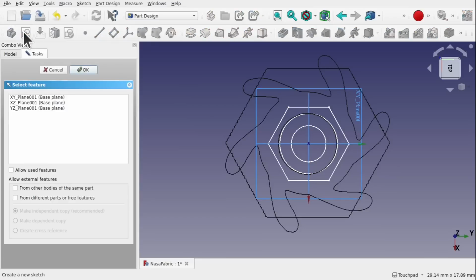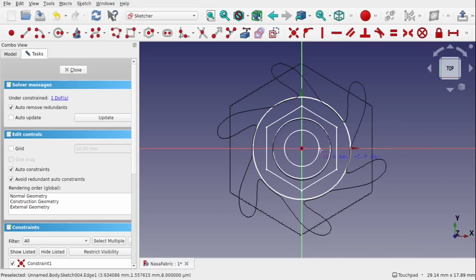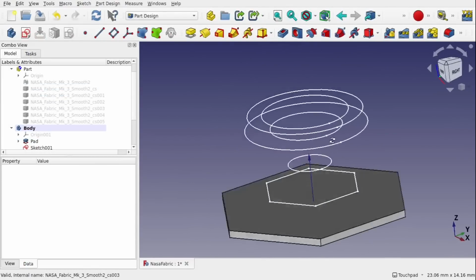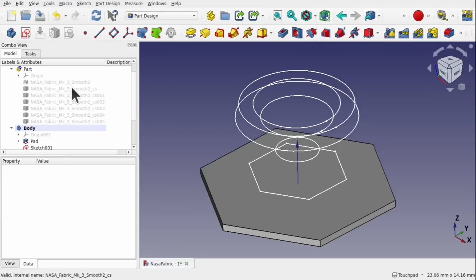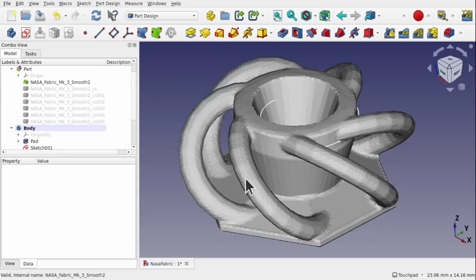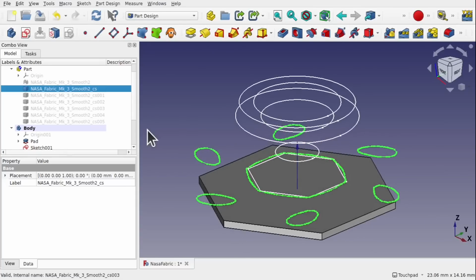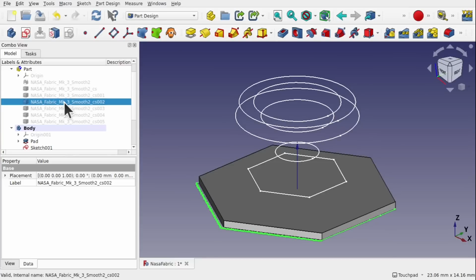Let's create a new sketch. XY plane, OK that. And again, using the circle, constrained to the center, coming out, and we're looking to touch this circle around here, not worrying about these arms that are radiating out. So moving forward, I've created all the sketches in here, all the individual sketches for those parts. So if we bring back the shape, we can see from the cross sections, now we've got this one down here. We've got this, which is part of that pad.